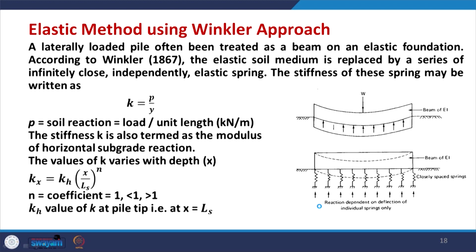According to Winkler, the elastic soil medium is replaced by a series of infinitely close, independent elastic springs. So, these will be elastic springs, not one, a number of springs will be there. The stiffness of these springs may be written as K equal to P by Y.